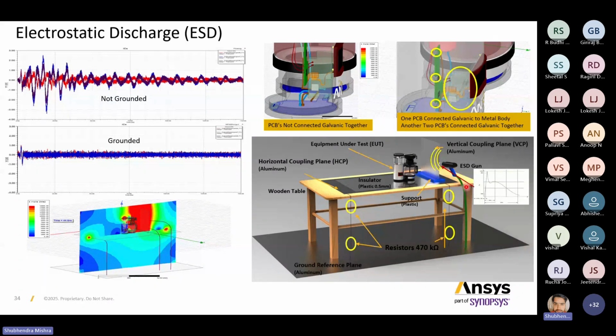And this is our proper setup. In this, you can see there is an ESD gun. From this ESD gun, we are incident a plane wave on our EUT. For the first application and the second application, we will analyze the noise after this. I'm putting this ESD gun, those RF signals over our EUT.